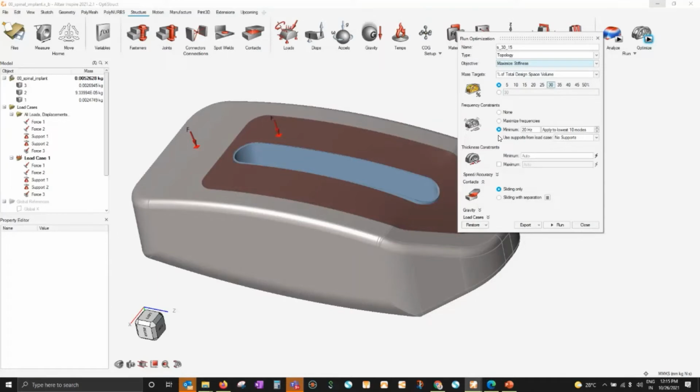But on the other hand, for example, a component which is mounting an engine: the engine has a certain frequency, say 36 hertz. Now you, as a designer, would target your engine mount bracket's frequency to be much higher than the 36, right? Normally people do 2 times or like that, so that it never resonates during the course of going from 0 frequency to that 36 hertz frequency of the engine, right?